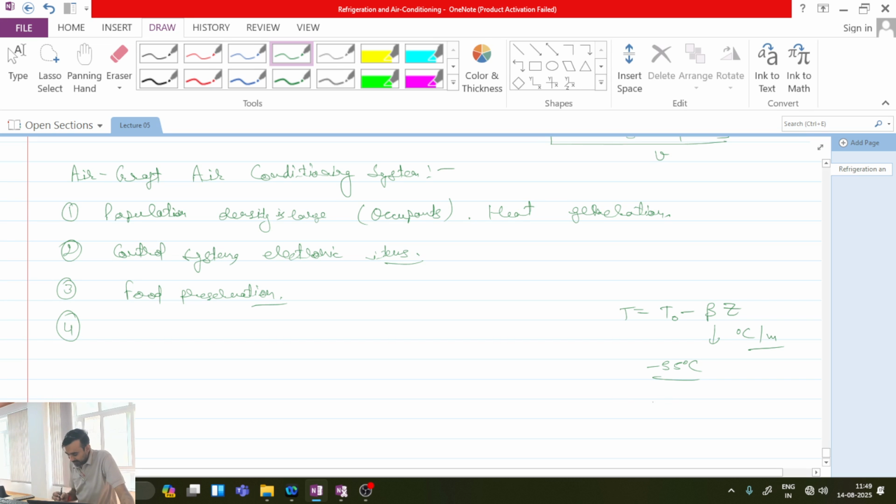Ultimately, at the body of the aeroplane, I will have formation of a boundary layer, which leads to relative motion between the different fluid layers, and as these have finite viscosity, we will have generation of heat due to viscous dissipation.